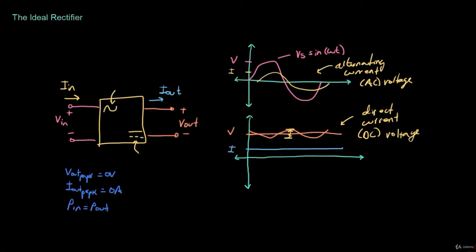So you would want to have some means of converting the energy from alternating current at the power outlet in your house into direct current such that the computer can use it. So that's why rectifier circuits are very common in power electronics, and almost any power supply that is used to power electronic equipment has a rectifier in it.